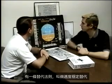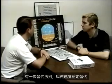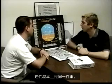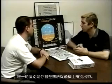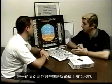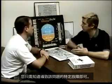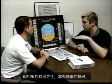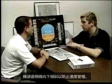Okay. There's an alternate law that's called alternate with speed stability and alternate without speed stability. They're basically the same thing. The only difference, and you're not even going to be able to tell from your aircraft, you just have to know a specific fault is going to cause that. But if you have stability, when you get slow, the nose is going to pitch down slightly to keep you from getting slow.